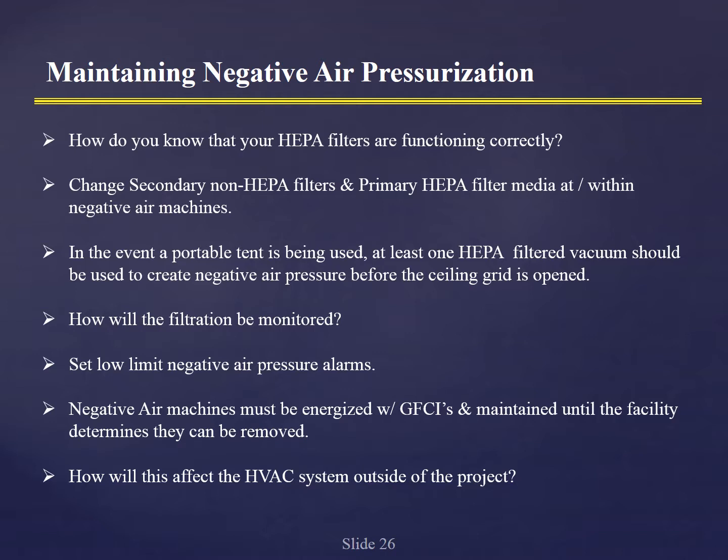Again, how will it be monitored? We talked about that before. Set low limit pressure alarms. This is one that gets us in trouble. You know, these low limit pressure alarms. The best we can sometimes do is create a little delay for the alarm while doors and things open. And it's one of those things you have to think through: how you're going to do it and how you're going to respond. And if there is an alarm, how do you follow up and document the follow-up?